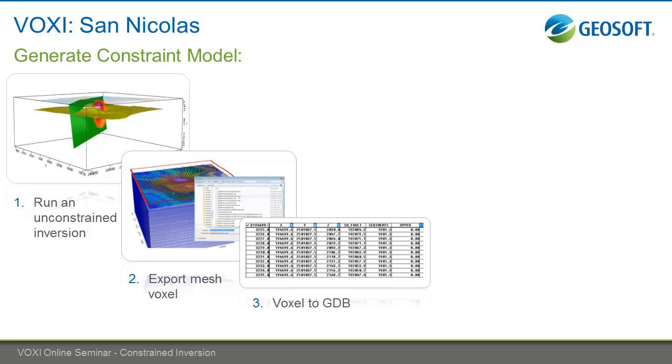Now, if I have my grid, which represents the base of the sediments, shown here in this yellow gold color, I can execute a sample grid to database. What that will do is take this gridded surface and sample it into the database. I've done that process and called it sediments.